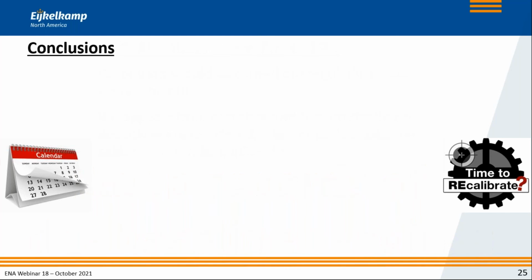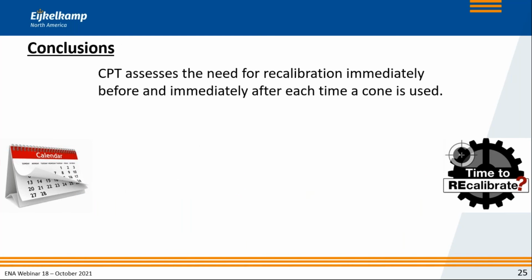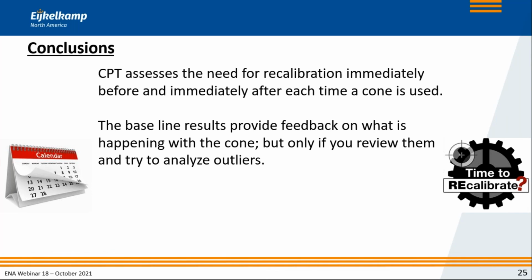So, what are the conclusions? You have to do a baseline reading before and after each time the cone is used. And on that basis, CPT assesses the need for recalibration. So we don't specify a recalibration period per se. Every time that we use a cone, we figure out whether recalibration is required, yeah or nay.